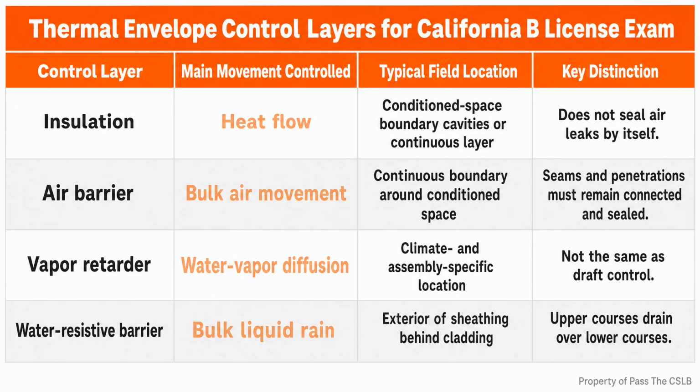Now let's get into it. The most important envelope decision often happens just before drywall. Once the wall is covered, a missing air barrier behind a tub, a loose bat, an unsealed attic hatch, or the wrong vapor retarder location becomes expensive to reach.